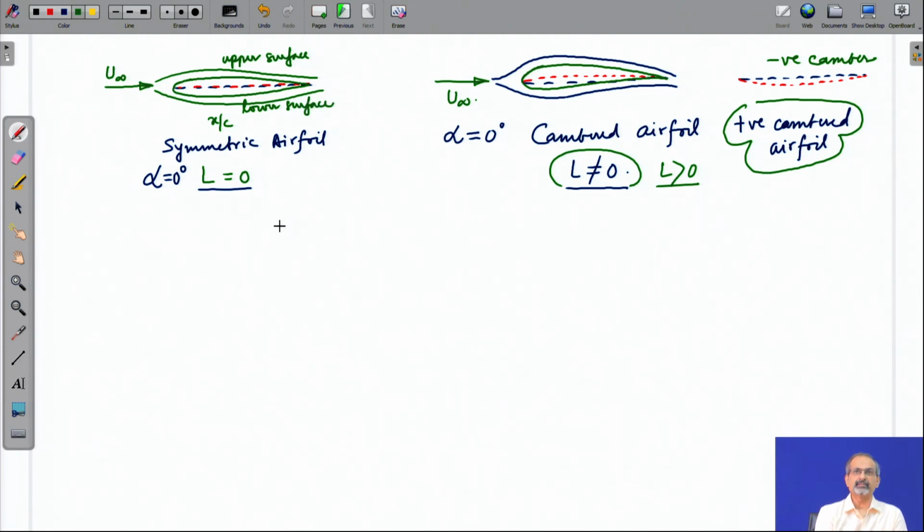One interesting thing is that if we are interested in looking at the thickness of the airfoil and identifying a location where it has maximum thickness, then it is easier done on a symmetric airfoil, because you can identify the thickness change along the length of the chord line much more easily because of the absence of camber. So, one may say by careful observation that this may be the location of the maximum thickness.